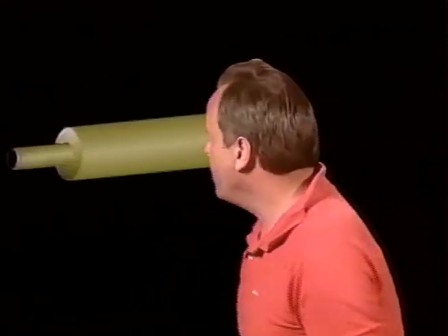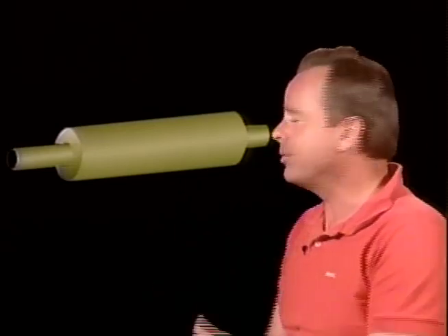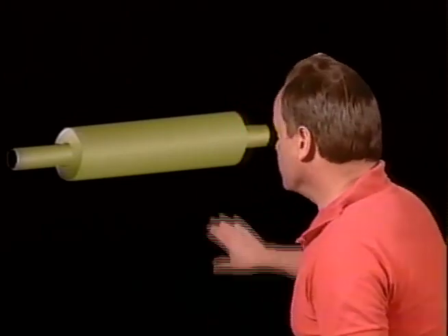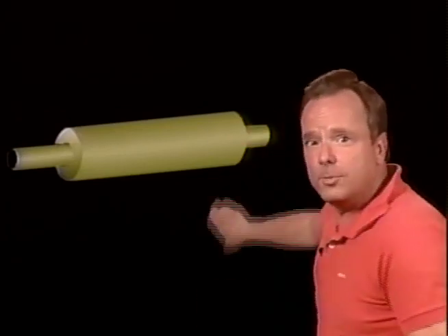Let's you and I take a look at a muffler. Now, if you have a muffler, inside this muffler, you know the way they muffle sound is by putting baffles, little plates with holes in them. Now, they're saying if one of these baffles becomes loose, and on the test they say dislodged, on a small reciprocating engine, it may obstruct the muffler outlet, and it could cause excessive exhaust back pressure. So if you have a baffle become loose, it could block off the exhaust and you have too much back pressure.